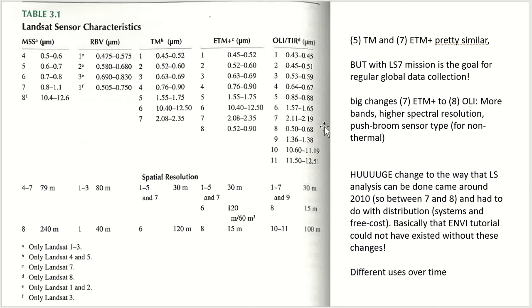Oh no, not 0.38. It doesn't have the same width, I'm sorry, but it is still imaging approximately the red and near infrared range, that being band 8 here, and has the same 15-meter spatial resolution. Landsat 8 has two acronyms here, OLI covering the multispectral bands and TIRS covering the thermal. And you can see bands 10 and 11, there are two thermal bands here.